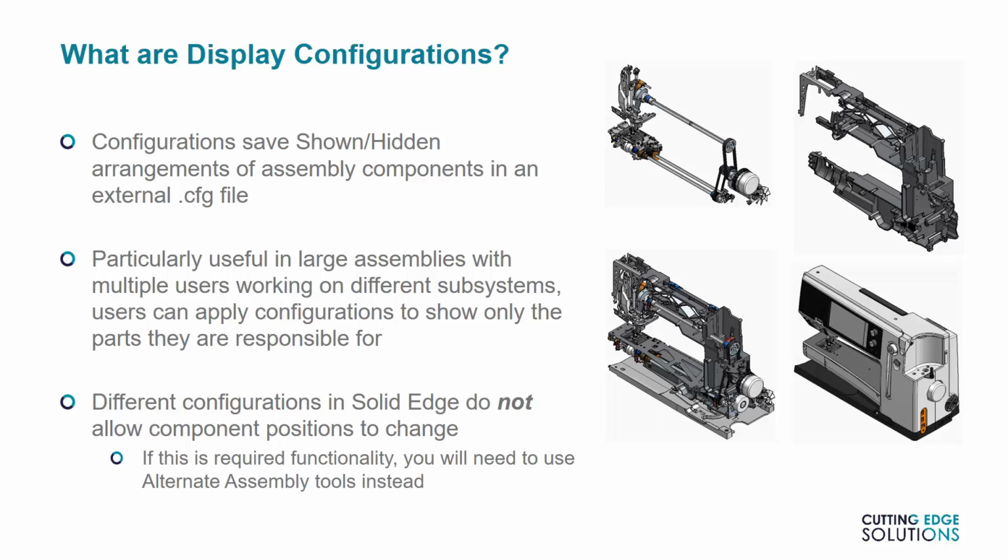Configurations are particularly convenient if you're using large assemblies with a mixture of components, especially if they're being worked on by multiple users. For example, a structural engineer might not care about seeing furniture in an assembly of a building while they work, and a drivetrain engineer might want to hide all other systems in a vehicle assembly. You can rapidly show the components that affect you, and then switch back to the overall assembly in just 2 clicks, providing you have the configurations already defined.